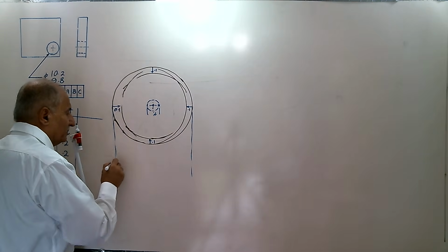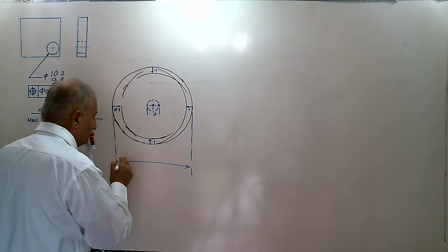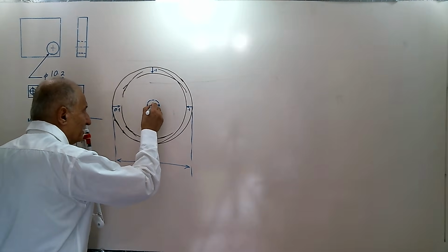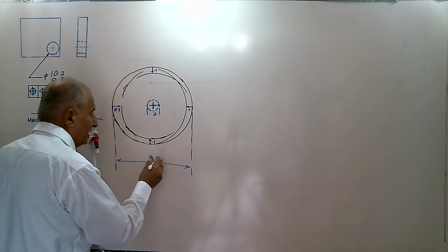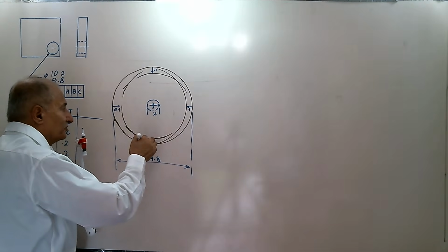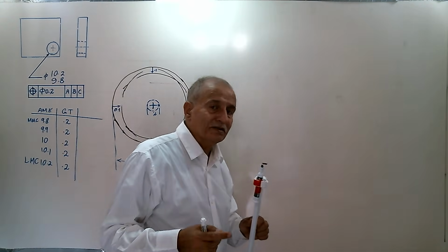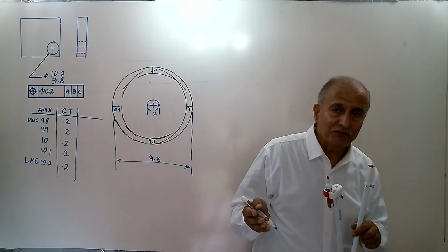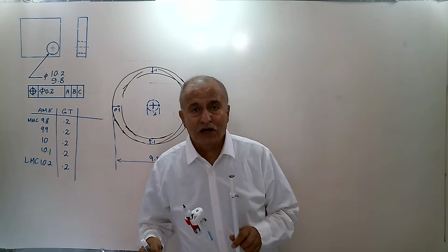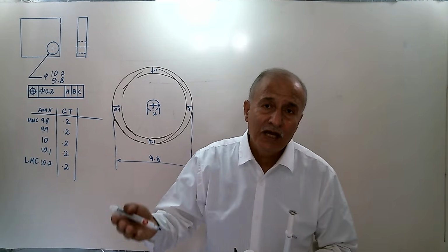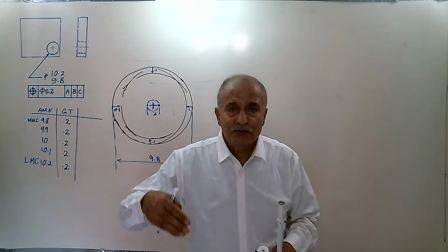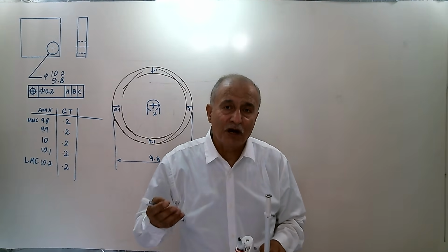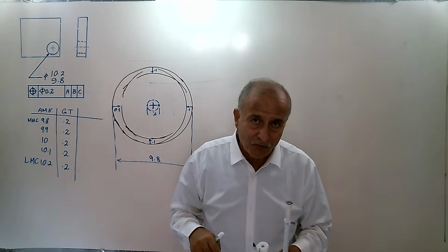That's the true ideal circle. It is impossible to drill a hole exactly at the true position. It is 9.8, but we came 0.1 from the side. For one hole, it is 0.1 right side. For another part, it is 0.1 left side. Other parts, 0.1 upward. Other part, 0.1 downward.